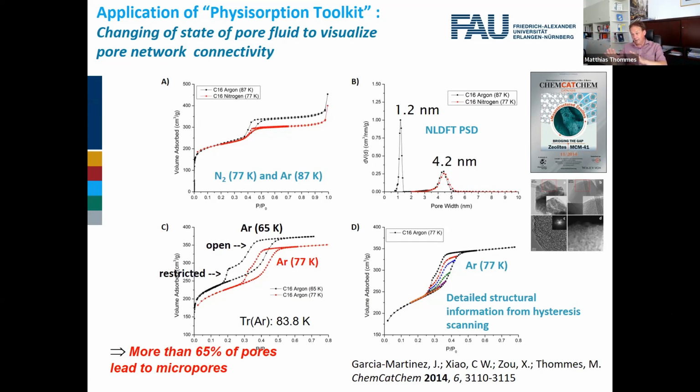But this is a very important result also, because then you can use this methodology to test wettability on a quantitative level, because the method depends on whether you have a wetting film on the surface or not. So if you know the surface area from other means, and you know that for your system immersed in the liquid this is the true geometrical area, you can obtain information about wettability. And I see, to be honest, the widest application for this technique there.